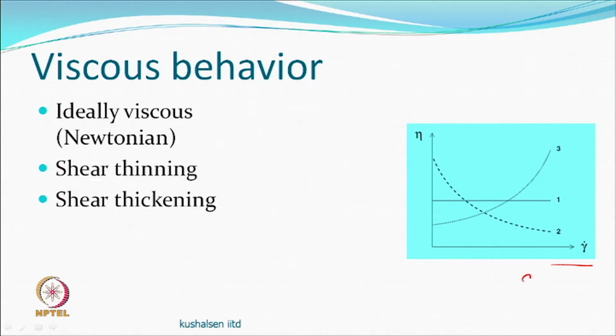So, liquids, which is a solvent first, then you dissolve something in them, and so their behavior in terms of the shear rate and shear stress and viscosity on one side if you plot. If it is an ideal solution, then this is the way it will behave, an ideal, all right. It does not matter at what rate you are pulling, because it appears each layer is independently moving, only you are worried about how much force I have to require. But very difficult to get an ideal